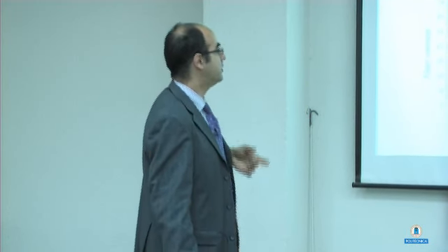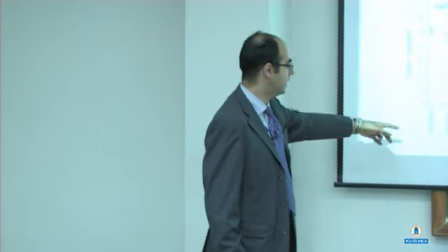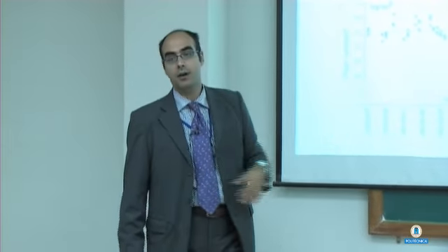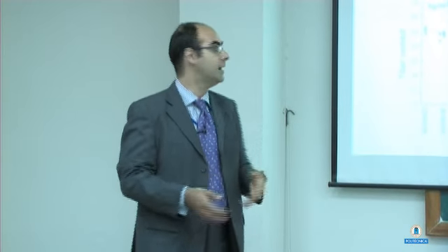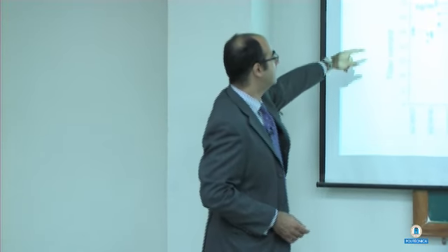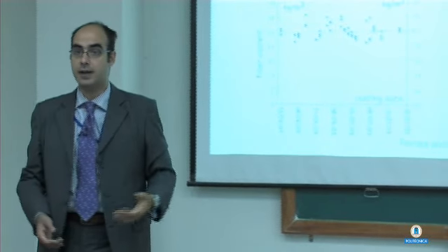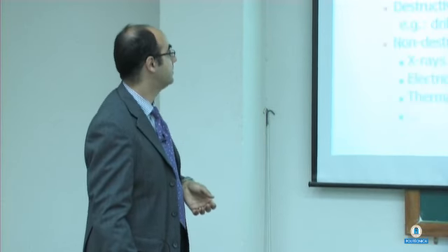After that, we went on to control the fiber dispersion. These data refer to the continuous manufacturing of roof elements I referred to before. You can see here, they date back about a month and a half. And this was a simple control of the fibers in the fresh state. Pick up a sample from the batch, wash out the fibers, wipe them, dry them, and weigh. And you can see that the target content is reasonably well guaranteed in the batch. But you see that when you go to the elements, you can have very wide variations.